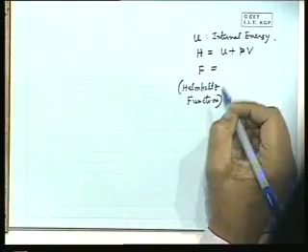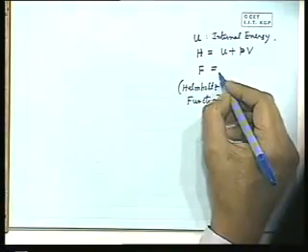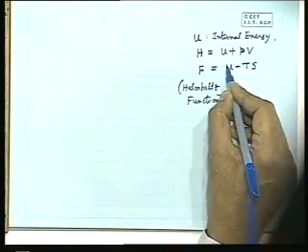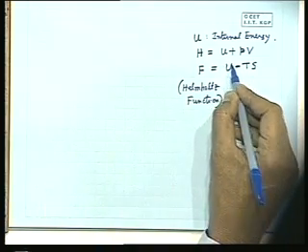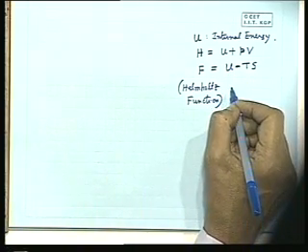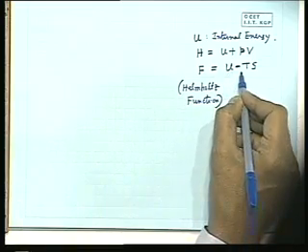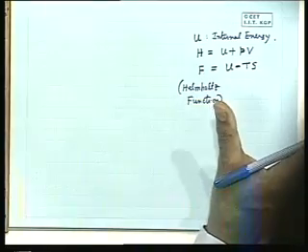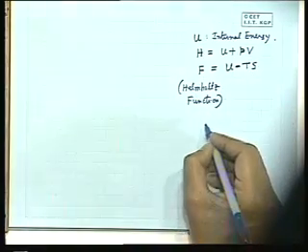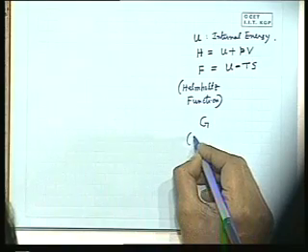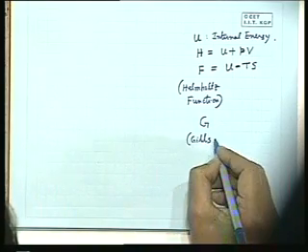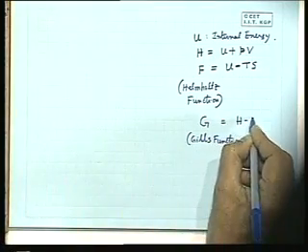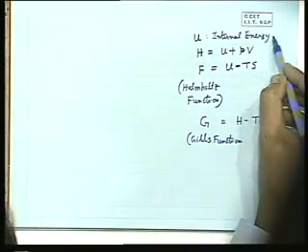So enthalpy is very similar to energy, whose dimension is energy, but is not exactly the energy. Similarly, the Helmholtz function is like this. That's why sometimes it is known as Helmholtz energy, whose definition is U minus TS. This is a system property. All these U, T, S are that of the system, because earlier we have seen that the availability function for a closed system is U plus P0V minus T0S. So there P0, T0 are the surrounding properties, not the system. Here F is U minus TS. Similarly G, which is defined as Gibbs energy or Gibbs function, is defined as H minus TS. These H, T, S are all of the system. That means they are all system properties.